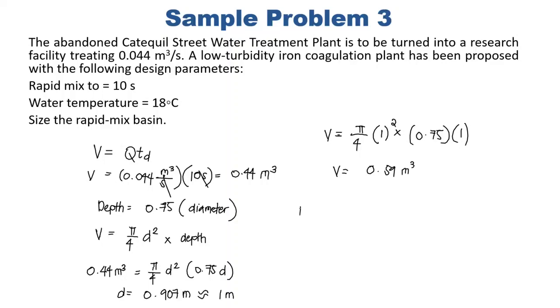Our detention time is equivalent to 0.59 cubic meter divided by 0.044 cubic meter per second. So our detention time is equivalent to 13.4 seconds.